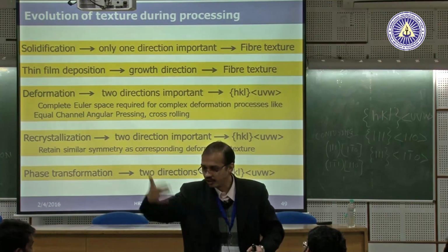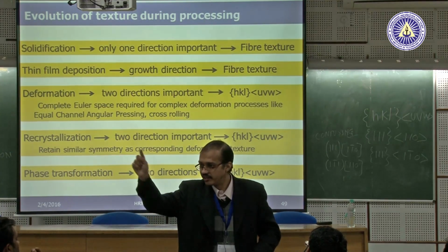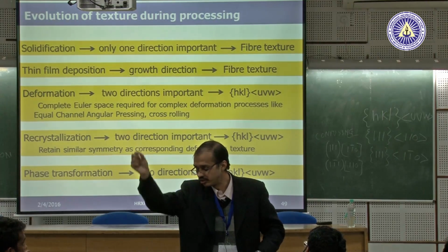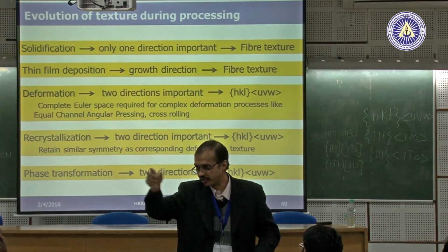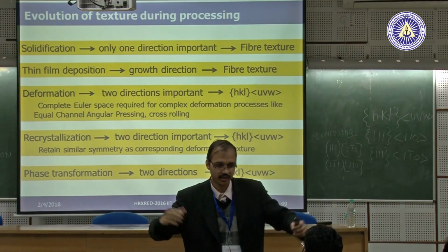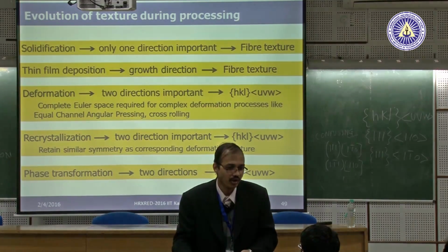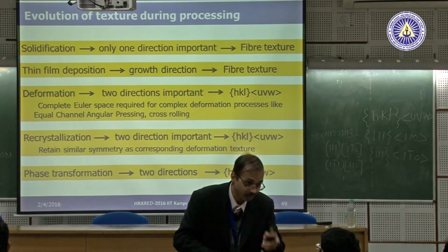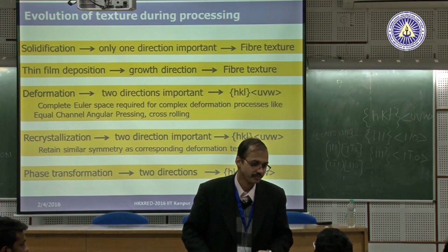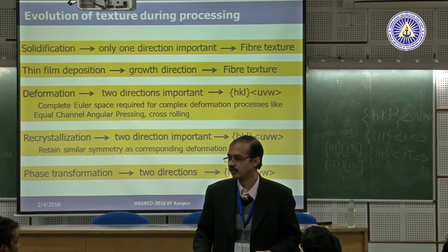If I look at this wall and if I look at the bottom wall, here I have columnar grains: the chill zone, then columnar grains, then equiaxed zones. They are in the horizontal direction here, and in the vertical direction there. But that's because of your wall. With respect to your heat growth direction, it's the same. So only the morphology has changed. But keep that in mind.